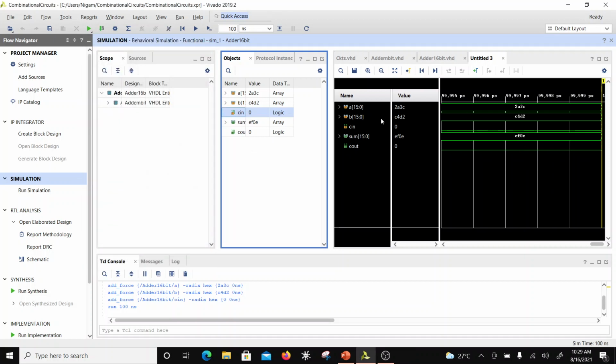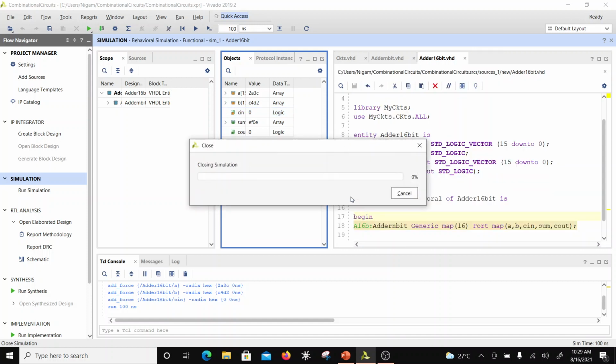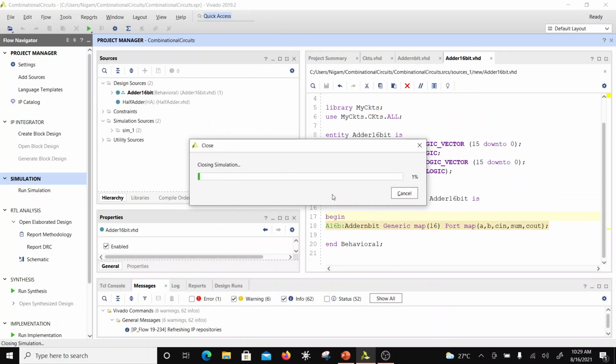So now you can see that you can write components which are scalable. Like we will write an entire ALU, arithmetic logical unit, just like this, so that we can easily modify the design to be 32-bit or 64-bit, right? That's a good practice to do. So I'm going to close the simulation window here. I've shown you how to use generic and generate.